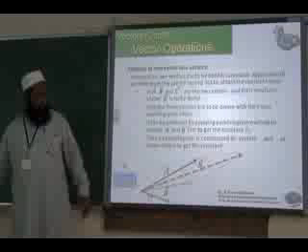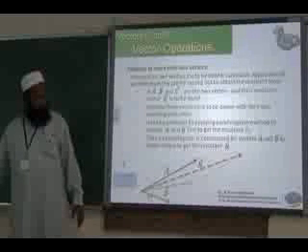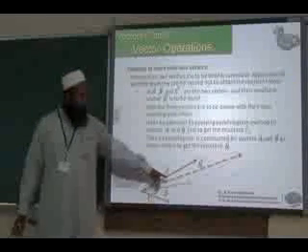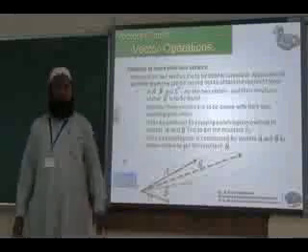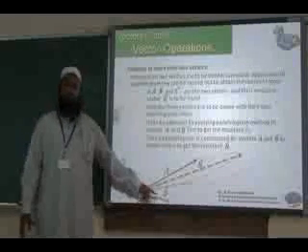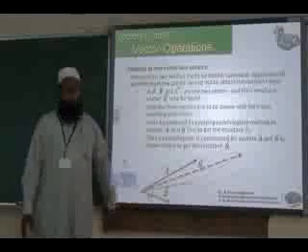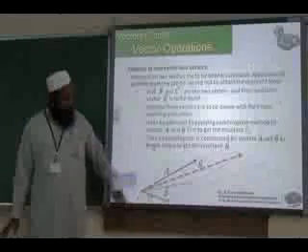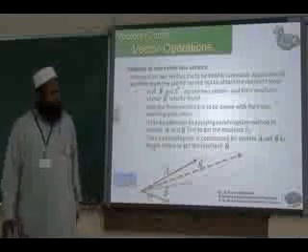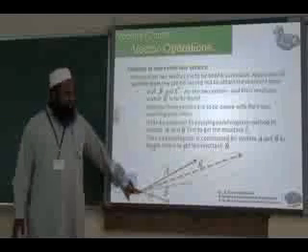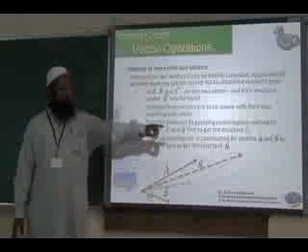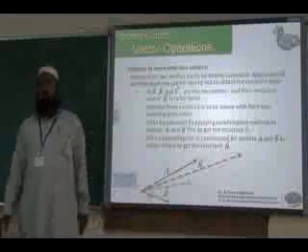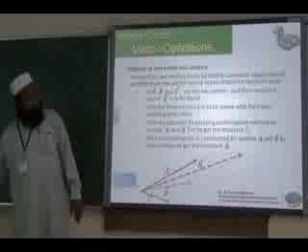Now, this is the line parallel to vector R, R1 otherwise. R1 is the resultant between A and B. So we draw a line from the head of vector C parallel to vector R1. Then another line parallel to vector C. Is it parallel? Okay. Now, from the concurrent point, we have to draw a line considering the parallelogram formed by vectors C and R1.